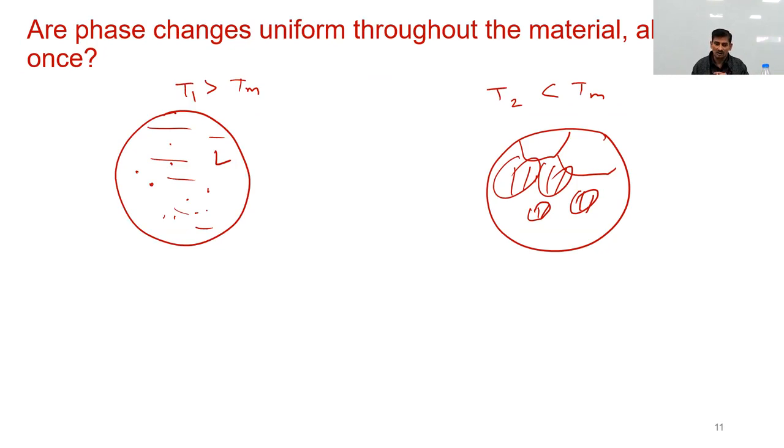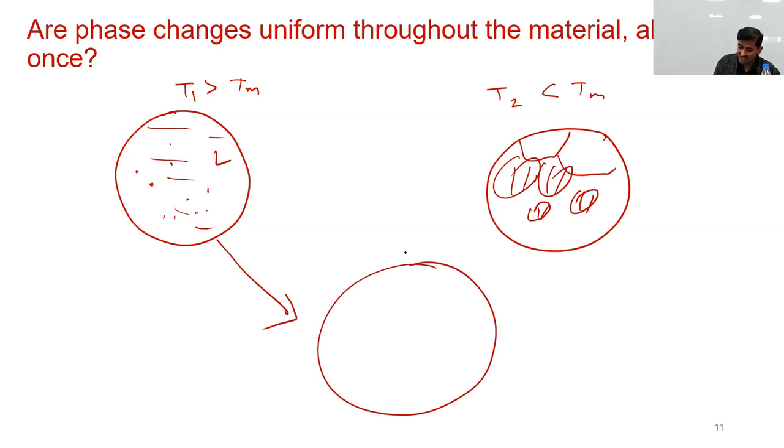That is the key point. As it happens, this particular scenario, where all atoms suddenly decide to come together and the entire volume of the material magically, instantly transforms into the solid phase, is not a very likely scenario. Instead, what happens is that certain groups of atoms come together and form tiny nuclei, and this is what we'll now be analyzing.